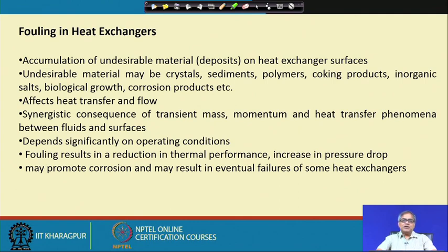Fouling results in reduction of thermal performance and increase in pressure drop. So, it is more or less an accepted fact that fouling will reduce the thermal performance, and that means whatever heat exchange between the fluids I could have expected at the beginning, for the base design or initial design of the heat exchanger, with time I will find that has reduced, and the pressure drop will increase.